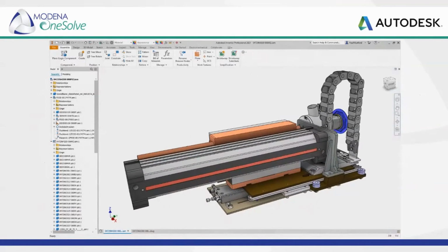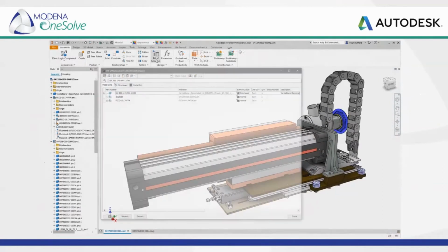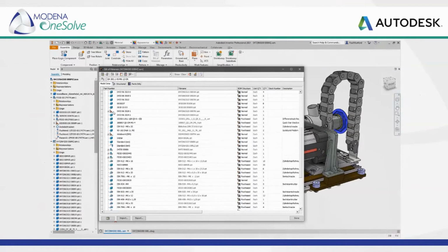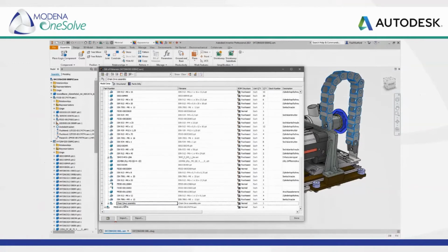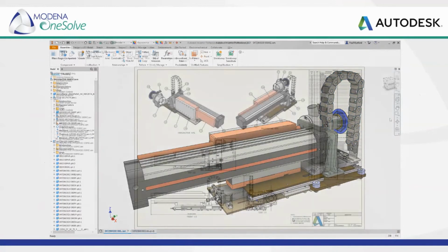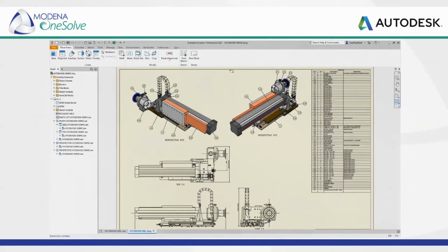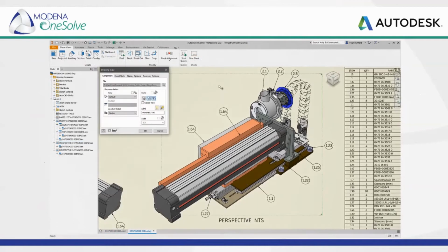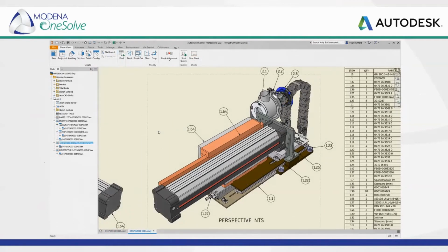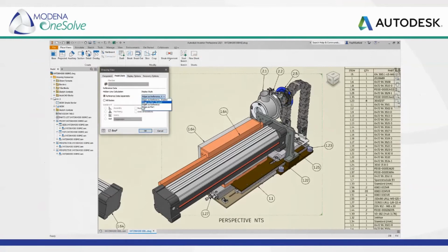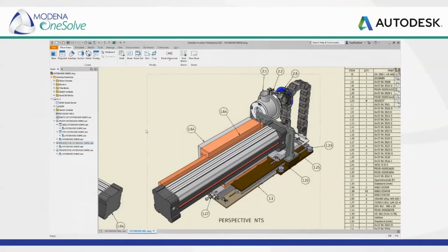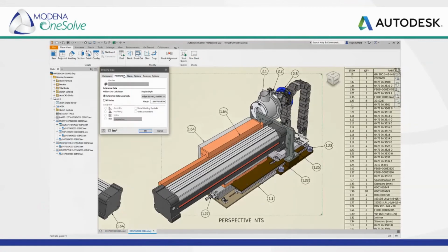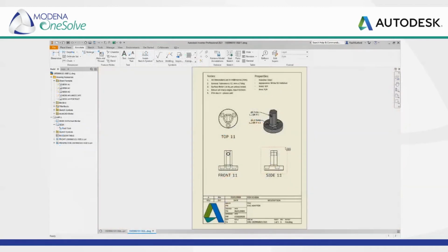Autodesk Inventor 2021 continues to deliver improvements requested by you and the Inventor user community. Through the Inventor Ideas and the Inventor Beta program, you provide your feedback to help improve Inventor with each release. Here are some customer-driven improvements for the drawing environment in Inventor 2021. Components set to reference in the Inventor bill of material have new visibility options in drawings, with additional options to show reference files in color and with or without dashed lines.